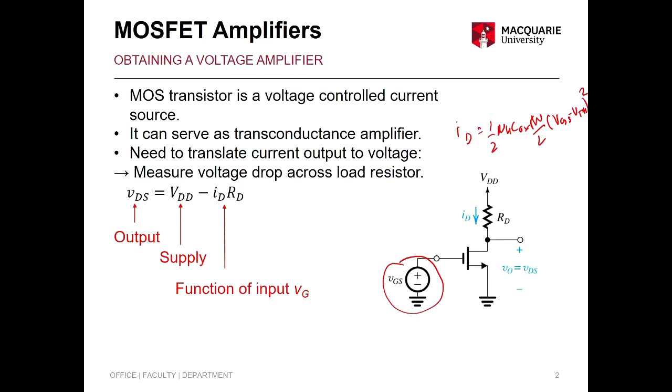Now what we are going to do is try to understand a simple amplifier. In your designs you could be using an amplifier stage like this. This is a single stage amplifier because it only has 1 transistor. It is also called common source. You have the gate, the drain, and the source. The source is grounded and there's nothing in there, and the gate is given a voltage, and based on that voltage there's a current that goes in the ID.